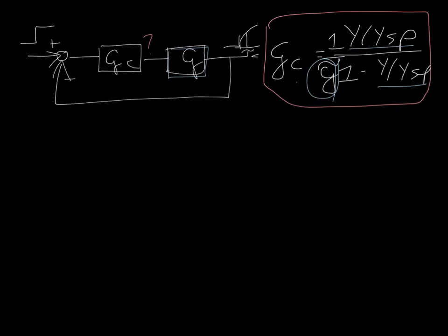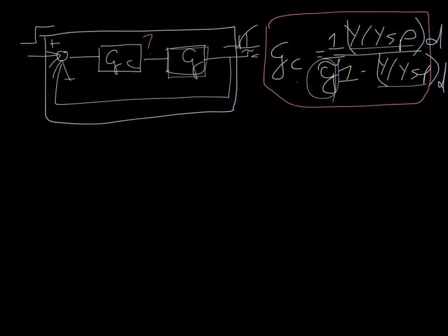So just before, I said that we may want to just use a first order desired output. So we may call this what we actually want. We can distinguish between the real one, which will actually happen, and what we want to happen by subscripting this D, so that we say that we have a desired output. And remember that actually this whole box, everything inside this box, is itself just a transfer function. So the closed loop transfer function that we have over here is just the relationship between the input and the output.